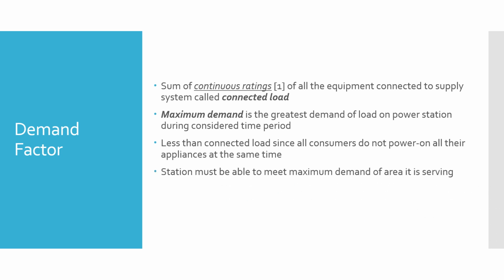Before we move on to demand factor, there is another thing about maximum demand: your power stations must be able to meet these maximum demands. They are not required to meet the connected loads, but they are required to meet the maximum demand. Demand factor is calculated based on this formula: the demand factor is basically the ratio of maximum demand to connected load.